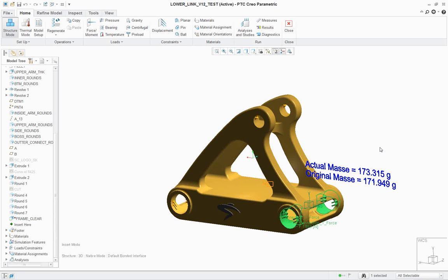Basically, what we just did there is, prior to this, we ran a mechanism analysis to figure out, due to rigid body motion, how the entire mechanism moves dynamically. And with this, what we're checking are the maximum loads at each of these particular areas that each component experiences. Let's apply that to the model, and then see how stressed the model gets during that mechanism motion.